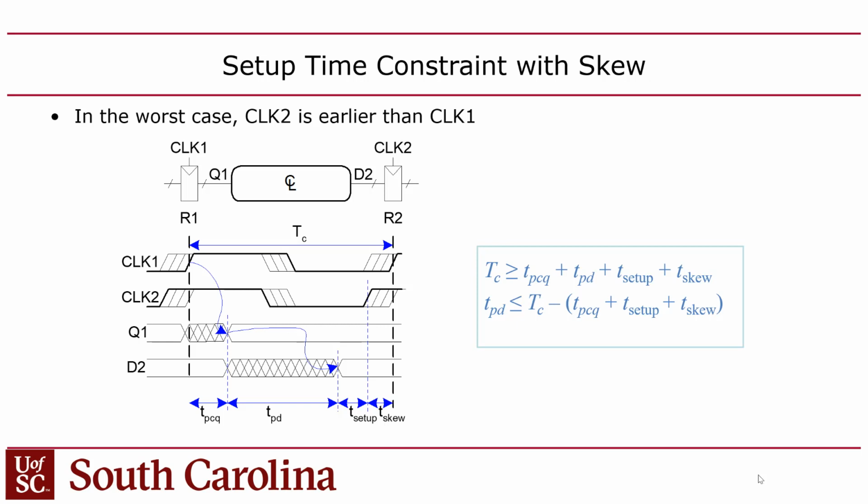So, for example, if this guy had a late clock, and this guy has an early clock, that's a problem for propagation delay, right? Because this guy is going to put his output out late, and this guy's going to expect it early, right? So that's why we add that here. This time t sub skew is the maximum difference between the clock at the two endpoints, right?